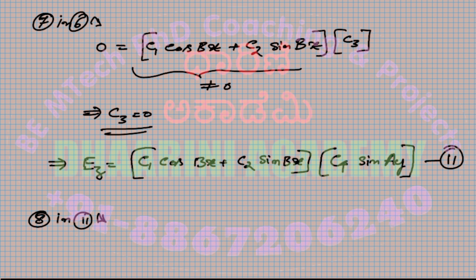Now you see the C1, C2, C3, C4 correspond to the same wave. That's why we are trying to solve it using the boundary conditions. So apply the second boundary condition to the updated wave, that is equation number 11. I know that in this case, once again, Ez is 0, so the left hand side becomes 0. That is equal to, so just look at the second boundary condition and tell me what I should write. The second condition, x is equal to 0, correct? y goes from 0 to b. So I cannot do anything, I have to keep it as it is.